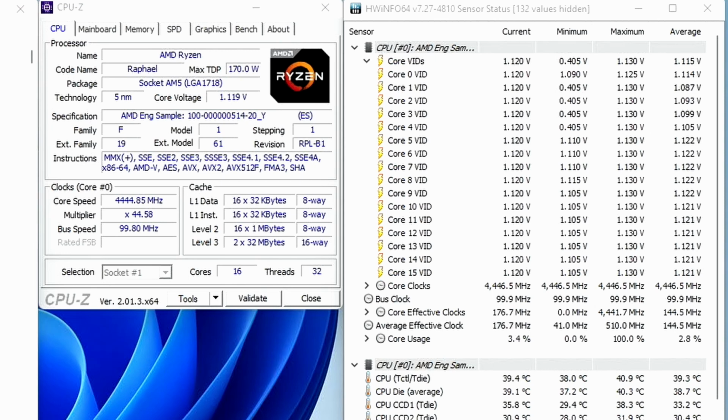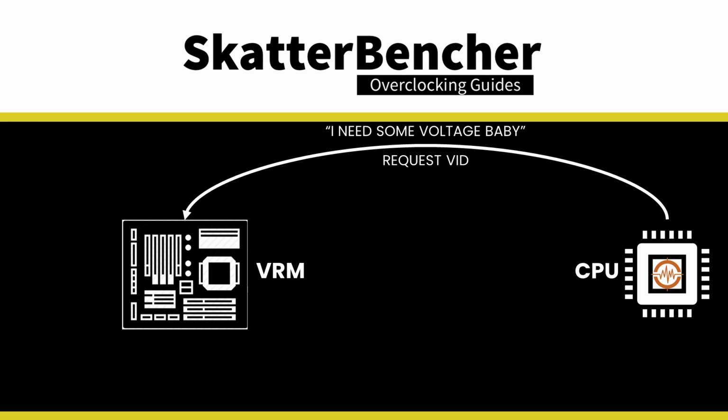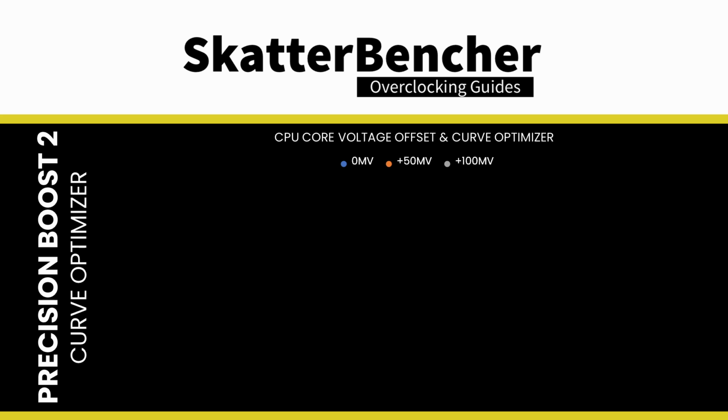I do this for 3 scenarios where I vary the voltage offset from the CPU vCore voltage regulator. As a quick reminder, the CPU will issue the voltage request to the voltage regulator with a VID request. The voltage regulator then adjusts the voltage output according to this request. When we use a negative curve offset, the VID request from the CPU is lower, and thus the voltage output from the voltage regulator is lower. We can also configure the voltage controller to add a positive offset to the VID request. Then the output voltage will be the CPU VID plus any offset from the controller. The 3 scenarios are 0 mV offset, plus 50 mV offset, and plus 100 mV offset.